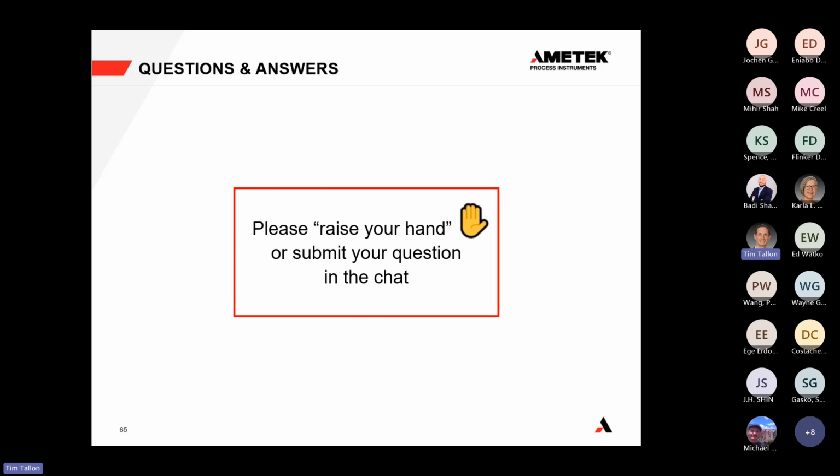Great question there. So the short answer is yes. The long answer is for a fired heater, it'd be one analyzer every 10 meters or every 30 feet. For a boiler, I'd probably recommend something similar. If it's becoming too big of a boiler and has many burners, I'd be mindful of how big it is and whether it makes sense to have one analyzer for a flue gas measurement, or do you need to space out maybe one every 10 meters or so?